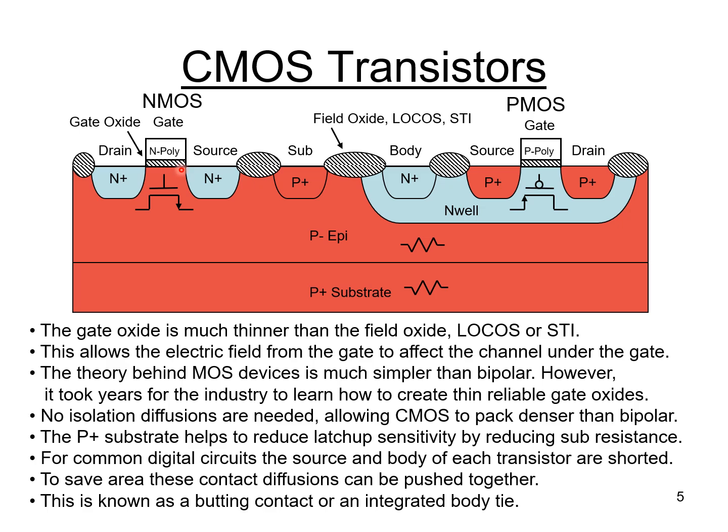I'm not going to get into great details on the theory of MOS. I'm going to talk about that in a later lecture, at least to some simplistic degree. I just really want to stick to the cross sections for this lecture. The gate oxide is much thinner than the other oxides on the chip, and if we look in between the contacts here, you can see some thicker oxide regions. That's often known as the field oxide, or LOCOS, which stands for local oxidation of silicon, or sometimes it's called STI, which stands for shallow trench isolation.